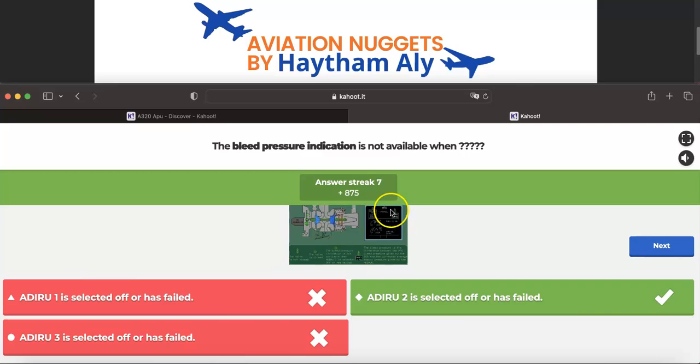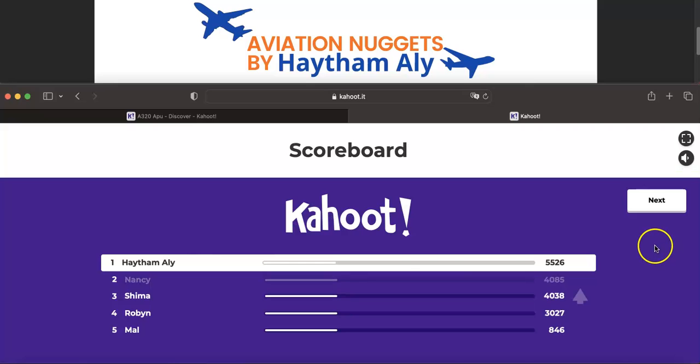This is because it is like a differential pressure, and the air data parameter from either U2 must be available in order to calculate the bleed pressure from the APU and display it on the APU ECAM page. Okay, everybody. Very good. Let's proceed to the next question now.